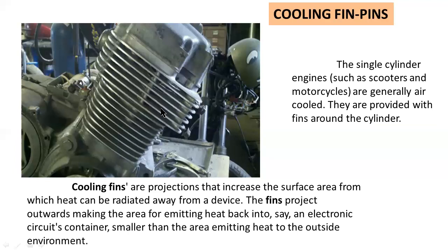The main function of these cooling fins is to transfer the heat from the inside surface to the outside surface. So here the thermal conduction property is very important for engine cylinder materials. The engine cylinder materials should have high compression strength, high thermal conductivity and low thermal expansion properties.